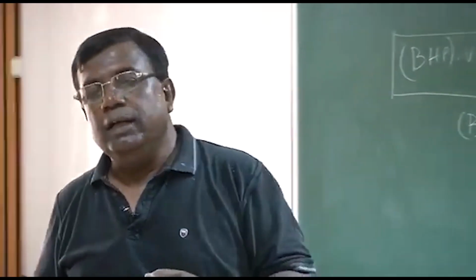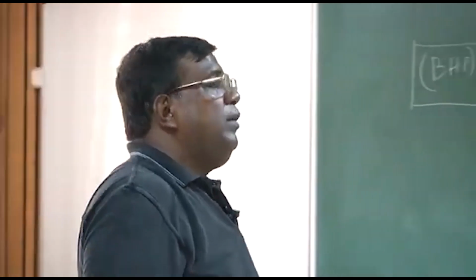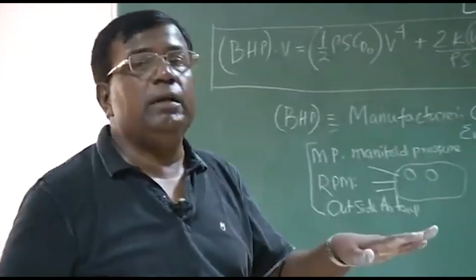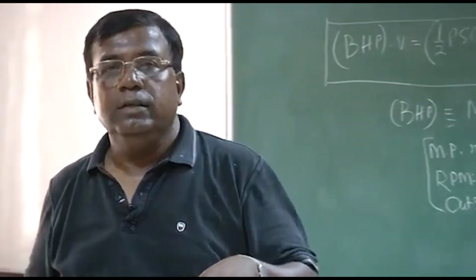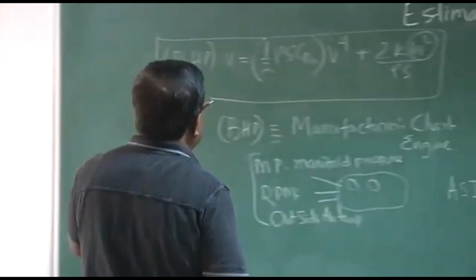From there, I use the fuel consumption chart to see how much fuel is consumed for that time and deduct that from the weight. This is one way. The second approach: when I land, I again weigh the machine with all the passengers and then take the average weight. And you'll find they will not be very far off. So this is how I get this information.